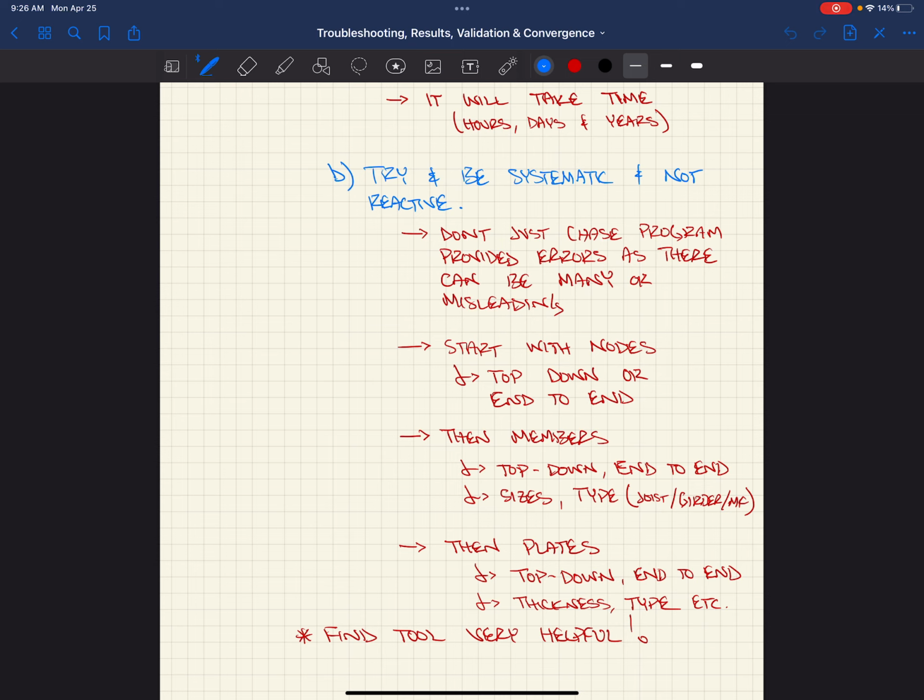Okay? So this allows you to be very methodical, right, with respect to nodes, or if I walked up to the next height, right, and I did model filter and I wanted to look at members. Right, now I have all the members on the second story. Okay? Pretty nice. So cut planes help you do some of that.